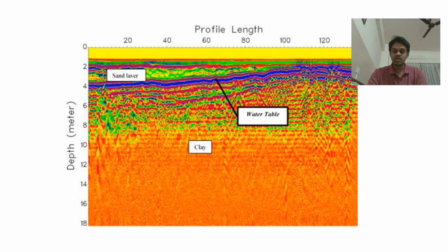Sometimes you can go for a shorter survey depth, or you can also go for some integrated methods which will help you in getting useful information. But compared to dry sand or rock, clay is definitely one of the toughest environments for GPR.